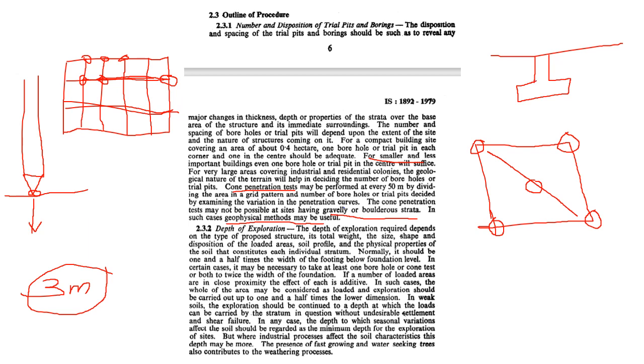Okay, you're planning to keep your footing at 2 meters depth, as recommended in the preliminary soil report. At 2 meters of depth, if your foundation is going to come, you have to ensure that you have sufficient bearing capacity at the layer where you are keeping your foundation.